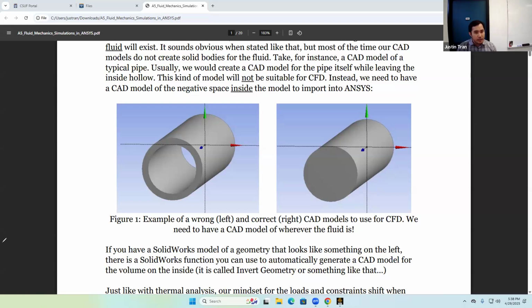If you have a fairly simple pipe geometry or a very simple valve geometry, this should work fairly well. But if you have a more complicated geometry where flow is going inside, outside, exterior, it may not work as well. So in those cases, you may want to construct your CAD model more manually. For fairly simple cases, there are some automated tools. Just be aware that there are some limitations.